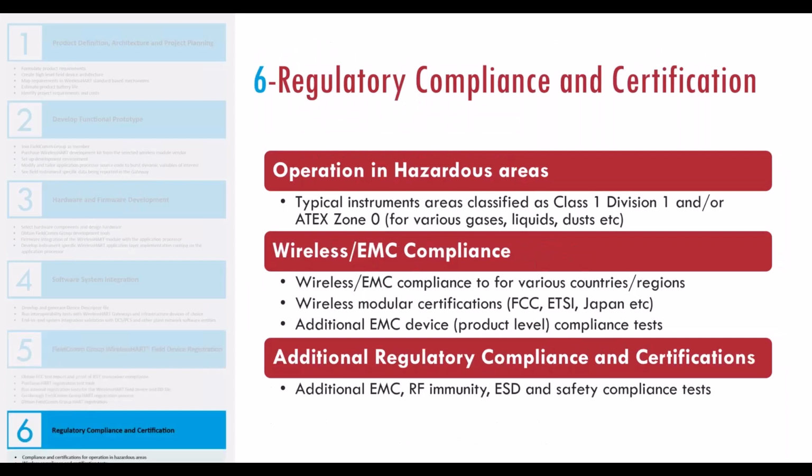Regulatory compliance and certification. Although this is listed as the last step during the development process, this is definitely something that you want to keep in mind throughout the entire development process. Obviously the operation in the hazardous area or the classification of your instrument will dictate the way you design your hardware, your enclosure selection, your antenna selection, and so on and so forth.